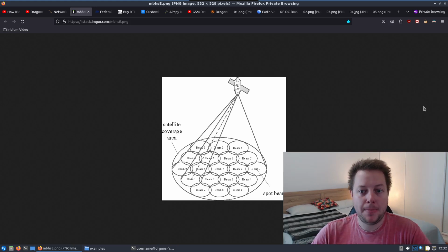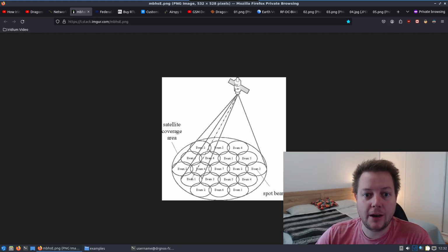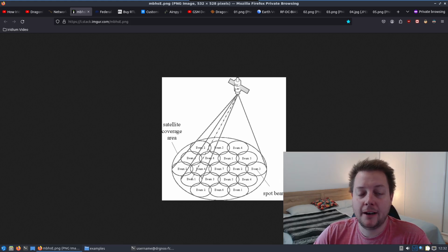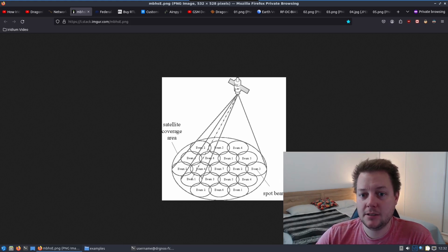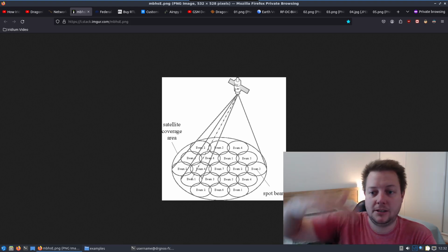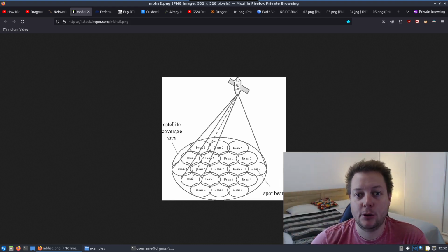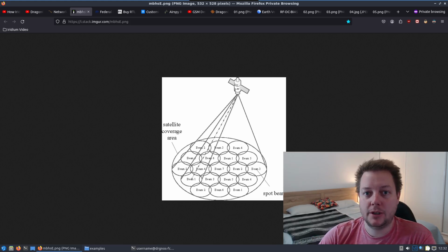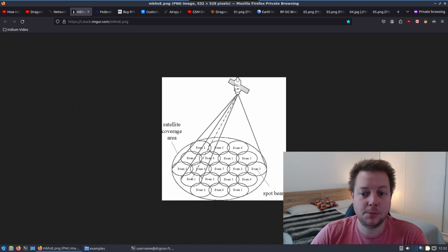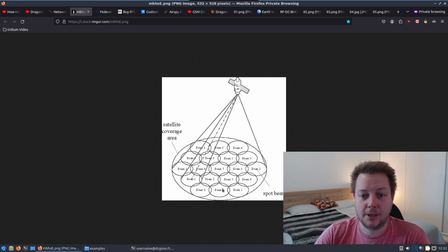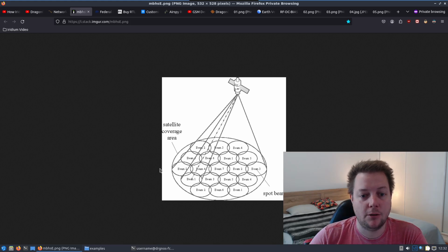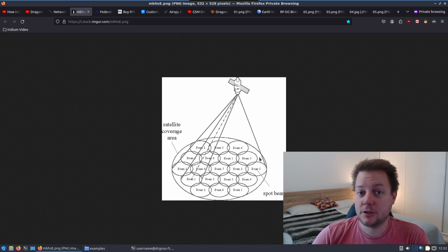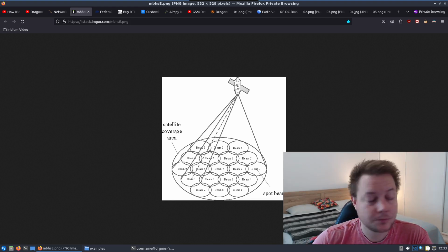Depending on the quality and performance of your radio receiving equipment and how good your antenna placement is, for example, your antenna is mounted high up with a clear view of the sky, not obstructed by buildings or trees, you should be able to receive data from Iridium satellites from an extremely wide radius around your location. Hundreds of kilometers potentially, and maybe 1,000 or more.